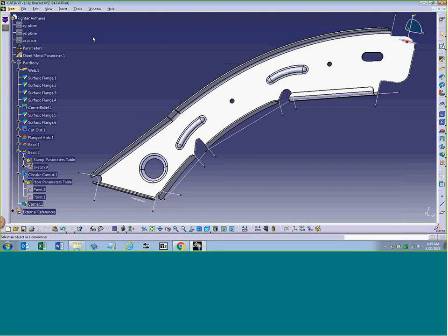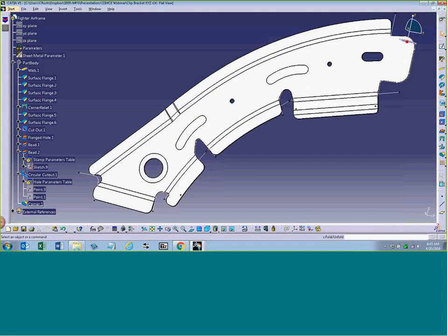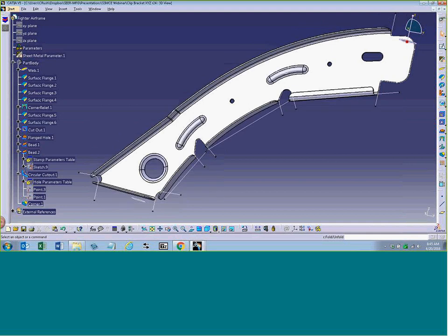The sheet metal interface itself, going into more detail, works with the aerospace sheet metal design interface and/or generative sheet metal design workbench. The parts contain what they call a web or a wall feature that determines that we're working in what's called the sheet metal type module in CATIA. When you're working in that environment, you can flatten the part and fold the part to see the start shape, and so on.